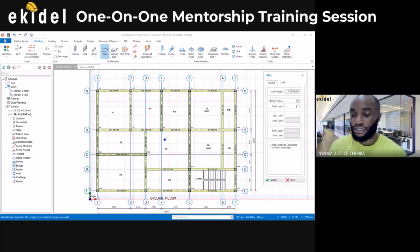So now you come here that says dead load. Now you can see dead load here and your imposed load. On this dead load, note that the value you are putting here is not a factored load. They are unfactored loads. Right? And for dead load, what makes up the dead load value is the finishing load and your partition load.